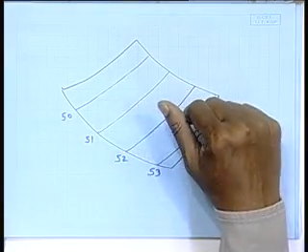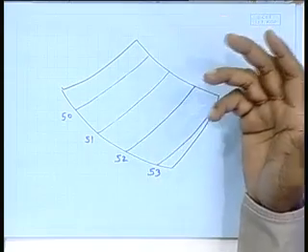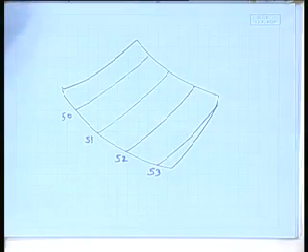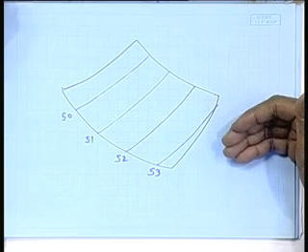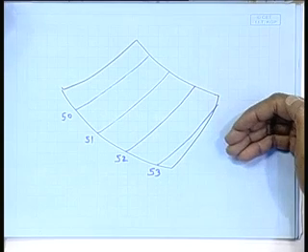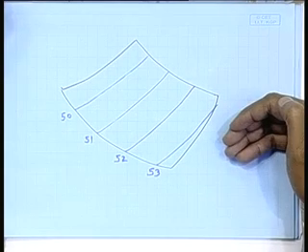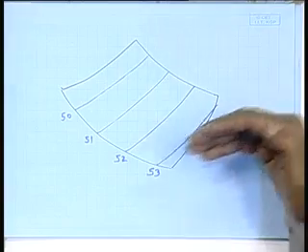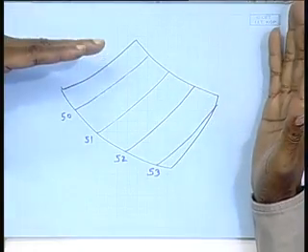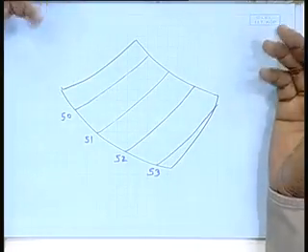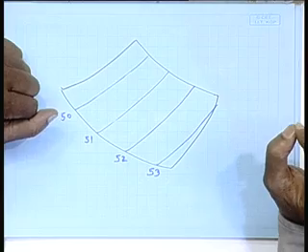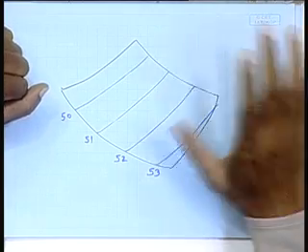So these are the areas where one can work and find a solution so that this process can be automated or improved, the production efficiency can be improved. That is one way of looking at it. The other way would be to produce a design wherein you have a minimum of curved plates, minimizing these operations.